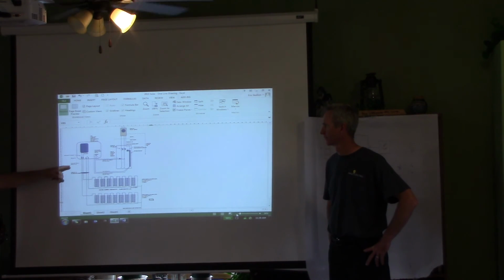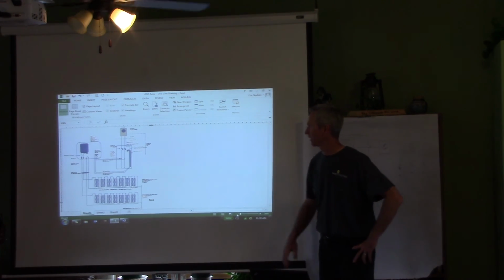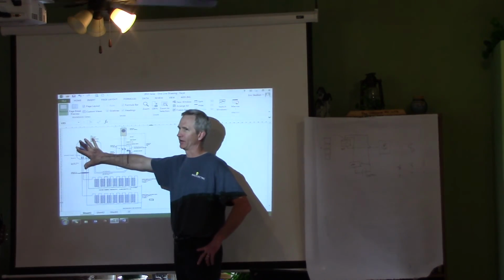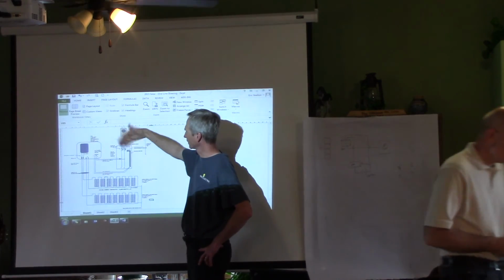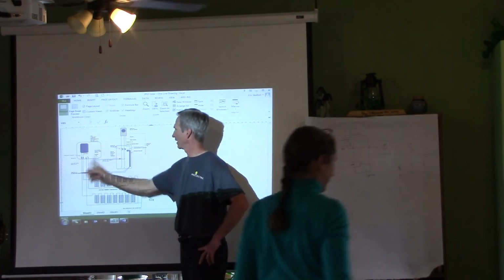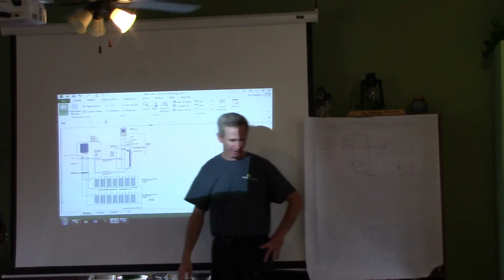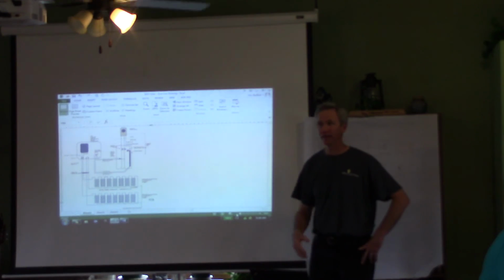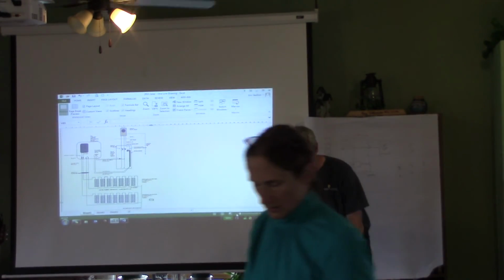Oh, solar panels. Uh-oh, I can't throw a tarp over the panels. They're going to want to shut that inverter disconnect off, because in their mind, they don't know that this inverter would necessarily shut down. So we've got the power coming in to the house shut off, but we still have power coming to the house from here. That could be problematic. In our case, with this Danfoss inverter, again, they don't know that, but it would not be supplying power to the house because power is not on the grid.